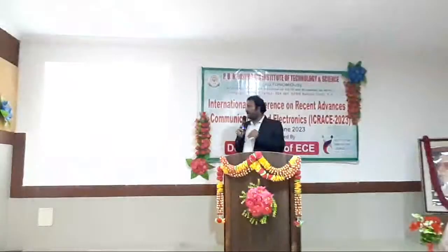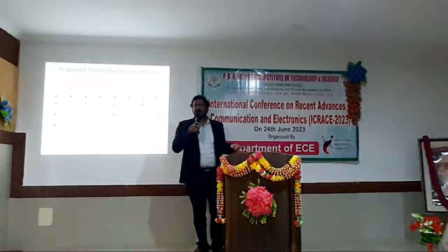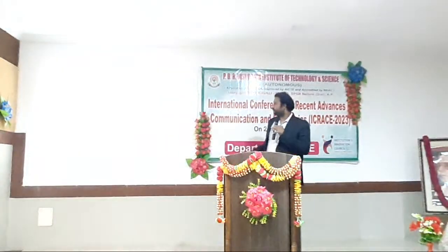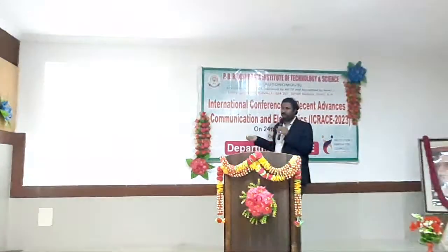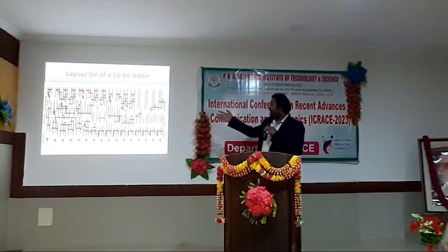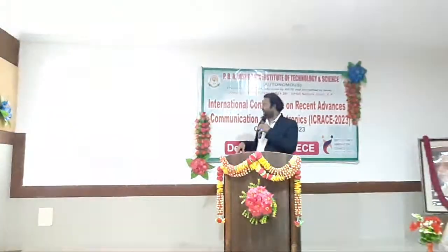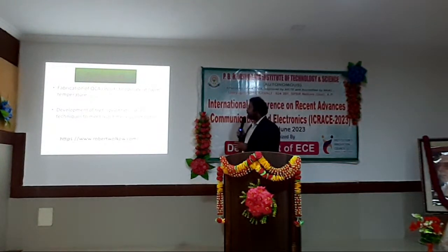So with this, I have proposed new majority gate based adders, which they should use. If majority gate is the basic gate, instead of AND and OR gate, they should use it everywhere. This gives 33% less area and 50% delay reduction. This is the QCA layout, the circuit looks like this. But there are some problems with fabricating this.